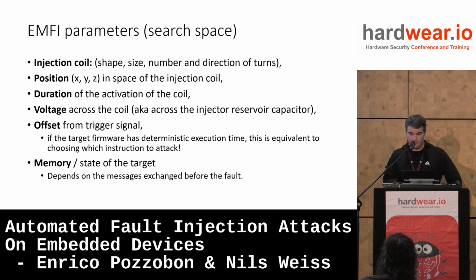And as a trigger, we tried different triggers, and one possible trigger could be the reset signal itself, so that we inject a fault sometime after reset. This sometimes works. However, usually it takes some time for the target to reset, so maybe it's not so fast.